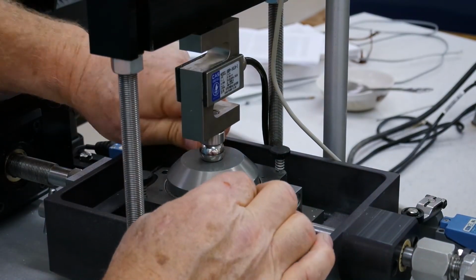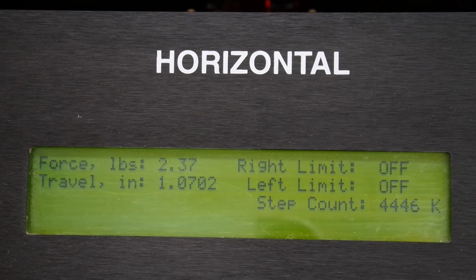We will be recording the horizontal load and displacement as well as vertical displacement. The vertical displacement may have positive or negative values, which will represent contraction or dilation. The horizontal displacement will remain constant. We will be taking readings every 0.01 inches of horizontal displacement until we reach the maximum shear load. And then we will take two readings after the loads start to drop off, or until we reach 0.25 inches of total displacement, whichever comes first.